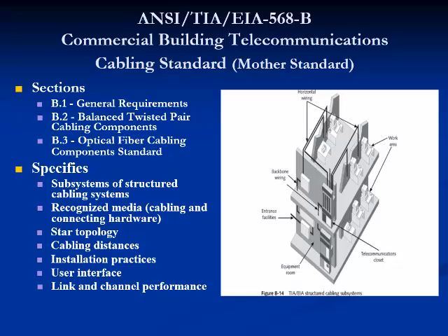The TIA 568B standard specifies subsystems of structured cabling systems, recognized media, and cabling connecting hardware, and that the cabling system must have a star topology. It recognizes and specifies cabling distances, installation practices, user interface, and link and channel performances.